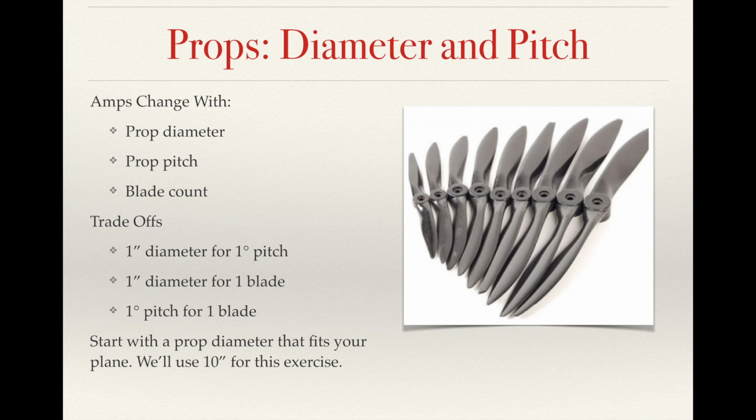Okay. Now again, I just want to say that in my experiments with props and watt meters and testing, these trade-offs aren't perfect across the board. They're not uniform. I'm not suggesting that every time you trade 1 inch of diameter for 1 degree of pitch, that your watts will stay exactly the same or your amp draw will stay exactly the same. They're just general guidelines. All right, that's it.